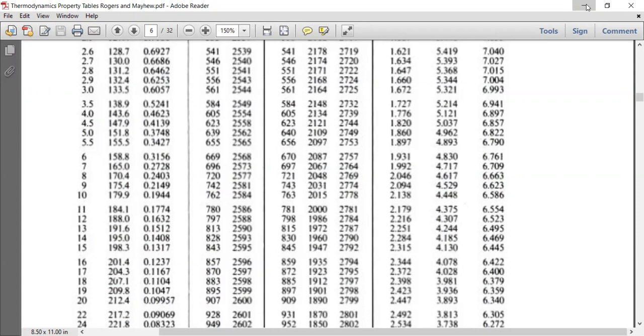So your T will be, very interesting, above the boiling point at 18 bar, means 207.1 C, more than that, so plus plus plus. Depending on the heat level, this goes up.